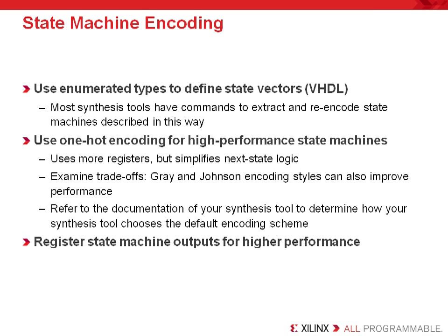Your finite state machine encoding is important for both size and speed of your design, especially if it is large and or complex. Most synthesis tools have commands to encode finite state machines when enumerated types are used. When synthesis tools make decisions like this, it is not always the best choice. I recommend building the machine and then resynthesizing for binary, one-hot encoding, and or gray encoding, and then compare the speed and the size of each of the synthesized state machines. After construction, this will take a little effort to test each encoding.